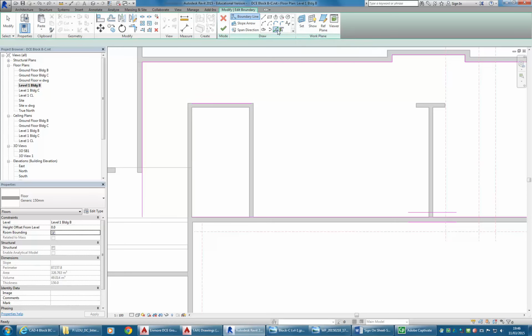But, again, if all else fails, use pick lines. Pick the edge you want, and if you really want it to stay stuck to that wall, just lock it. And it's basically the same as if you've used pick walls. So you've got those different options for joining your floors, or the floor's edges. But I'm going to go back and use pick walls.